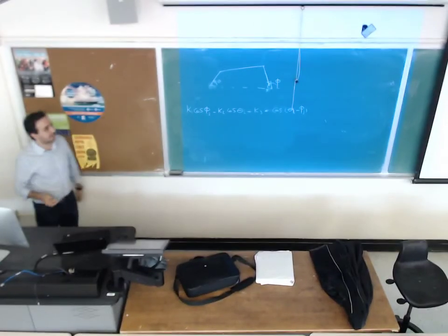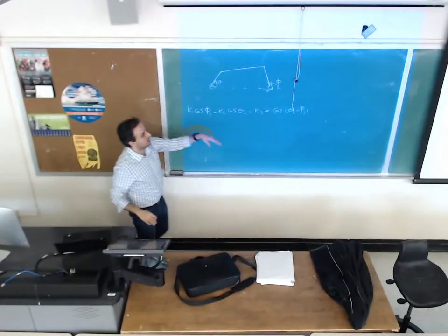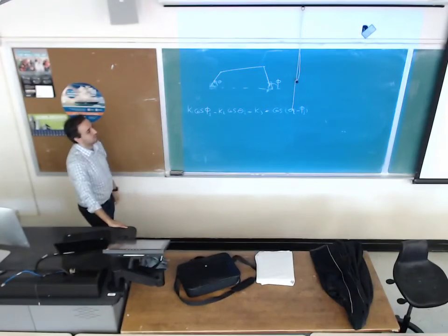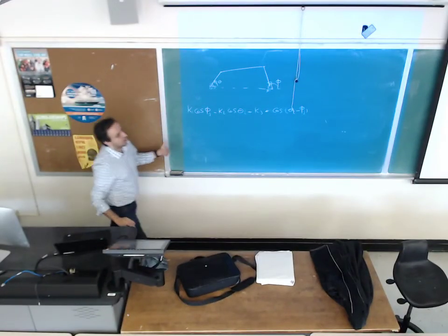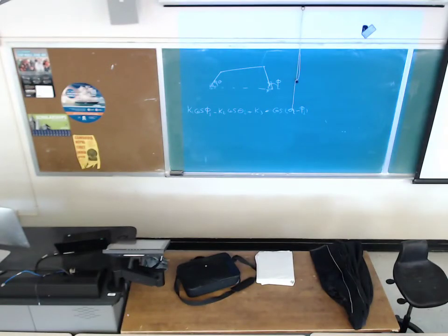If you remember, in that problem we had 3 precision points, and this equation should be satisfied at all 3 precision points. But what if we cannot go over the precision points? Then the left side is not going to be the same as the right side at all 8 precision points, or all 8 desired points that you would like to generate. In that case, this minus this is not going to be 0, and we define that as an error.